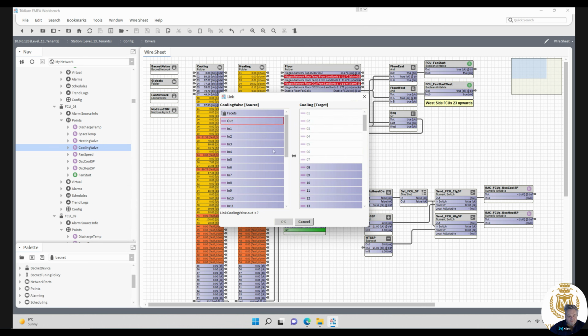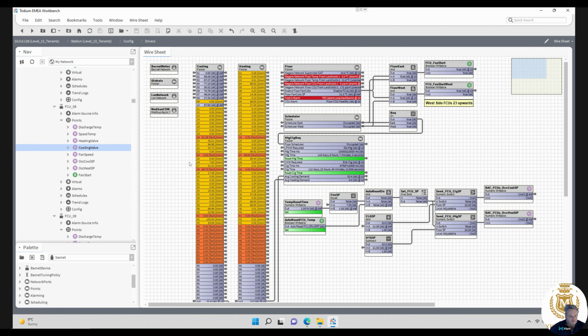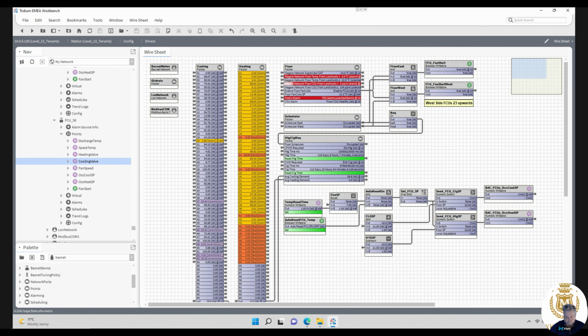So I'm going to put you on pause because this is going to be a long process. Just quickly show you this. Last fan coil was 56, which is in 54, and there's no more, so it's matching. So the fan coils are all there, all these points are correct, purely because I'm not missing anything at the end. With the same amount of fan coils in BACnet as there were in LON, all they've done is change the fan coil controllers out, so I'm not missing anything.